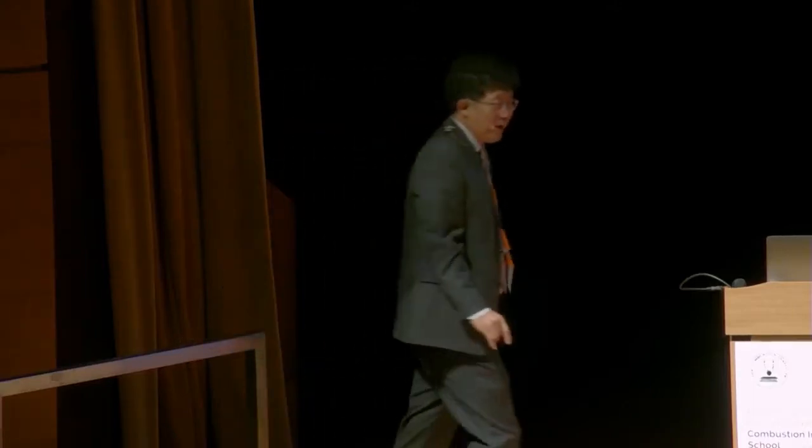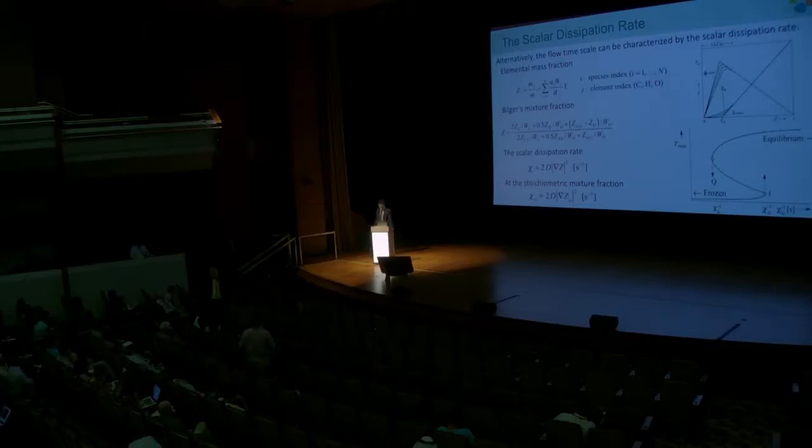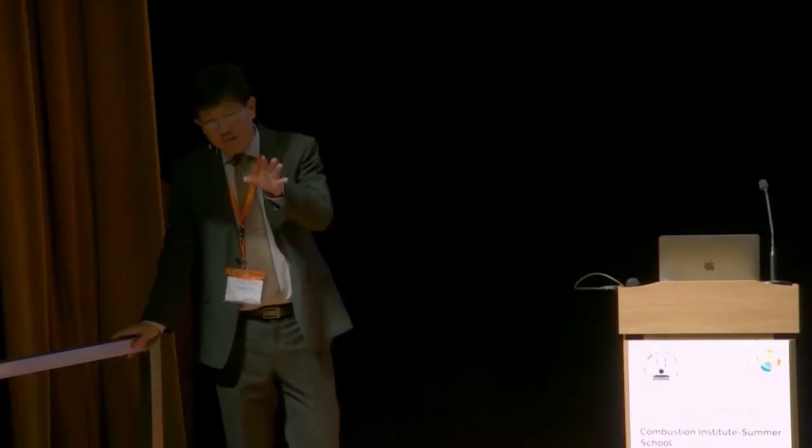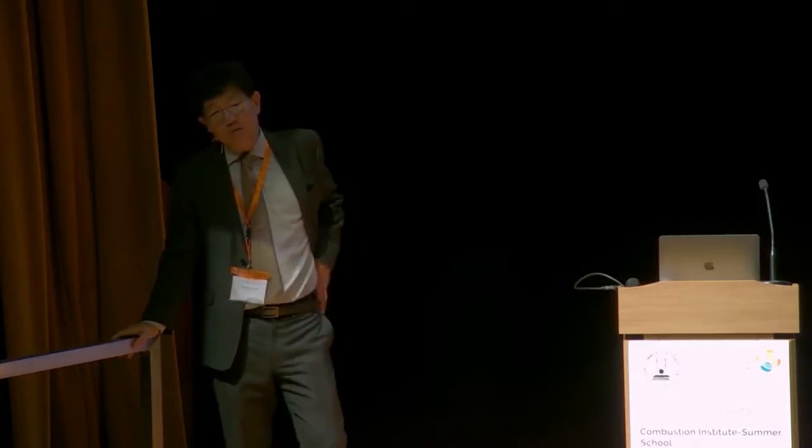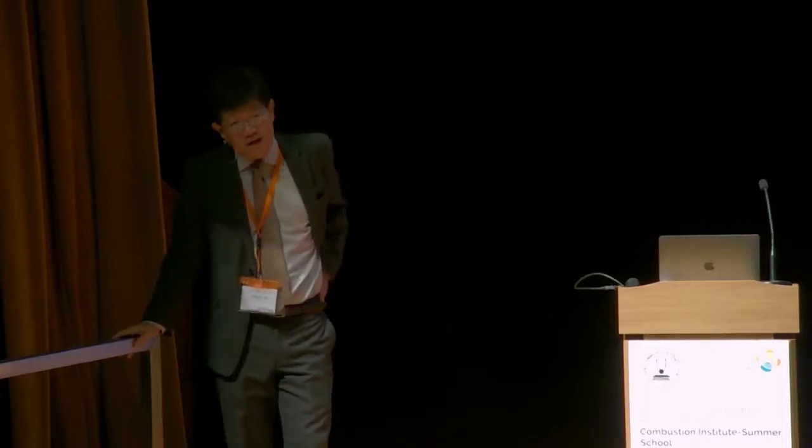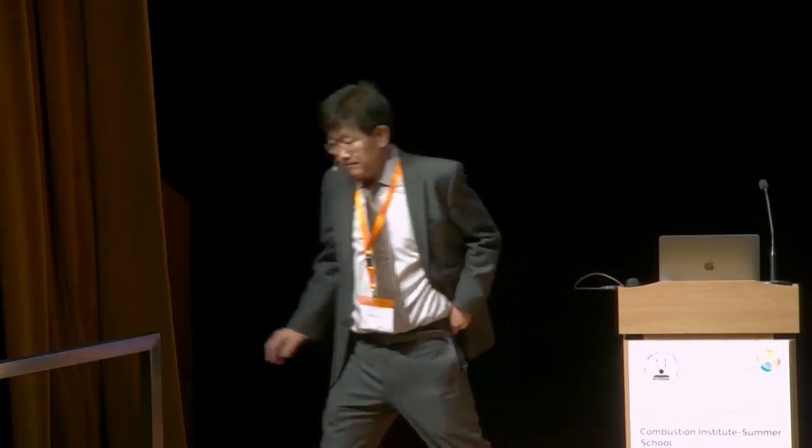completely different. So back to the spray, I don't know what exactly we're looking at, but spray is the same thing. My message is that you have to be a little bit careful whenever you're talking about flame disappearance. It doesn't necessarily mean the flame is extinguished. Depending on the context, especially in the case of a premixed flame, it can be just a flame blown out, which is different from blow off. Okay. Thank you. Yeah, thank you.